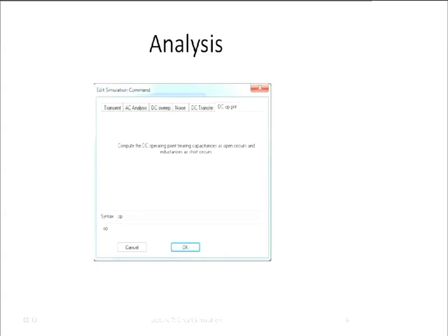There are other ones, like transient analysis as well. How do voltages change over time, right? Well, right now, we don't have any voltages that change with time. They're just constant. So we will get to the other analysis later. But right now, you just choose this DC operating point, say OK, and SPICE calls this .op, okay, from one of Don Peterson's students.